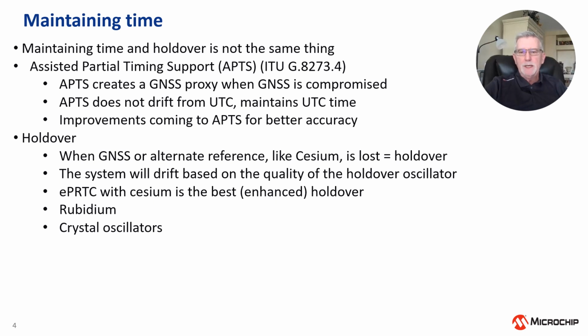If we have GPS reference operating at point A and GPS reference operating at point B, we can measure the exact delay in the forward direction of the PTP flow and back in the reverse direction from point B to point A, and know exactly what those delays are.